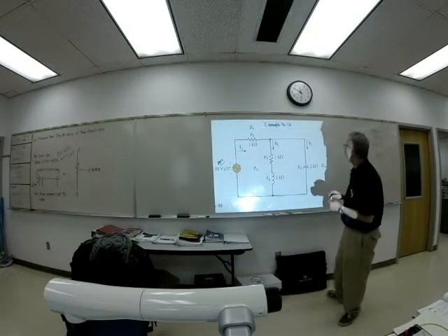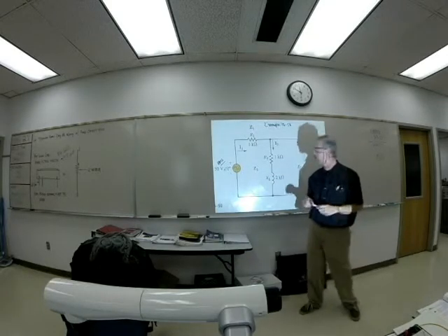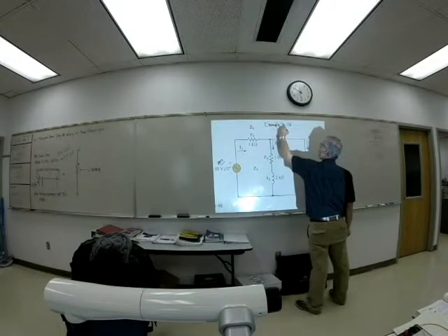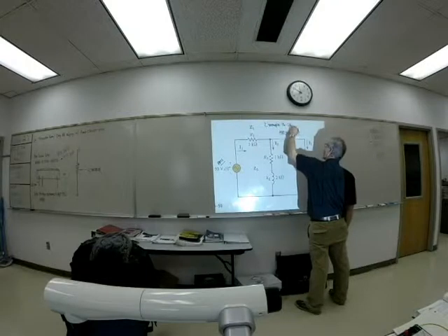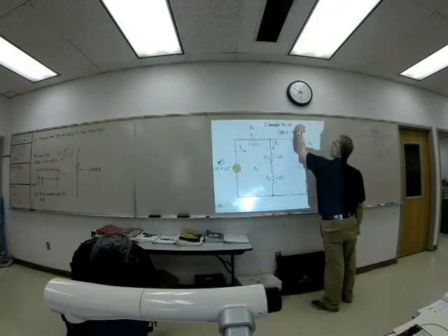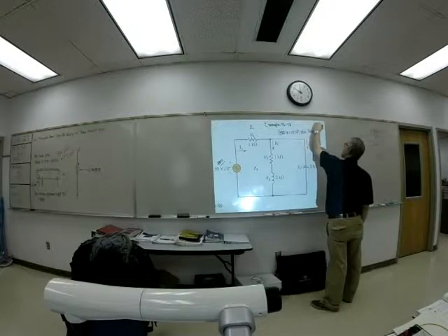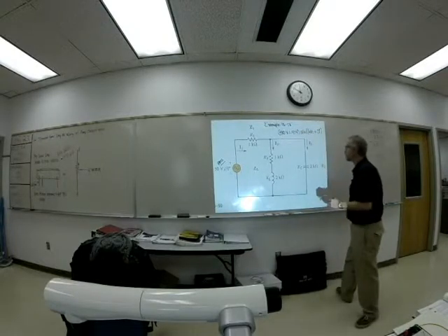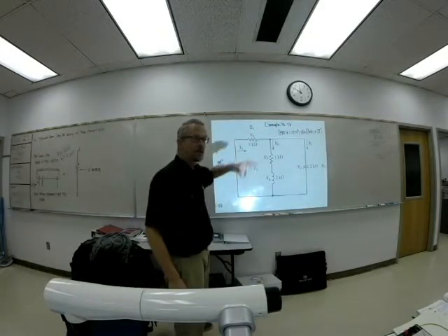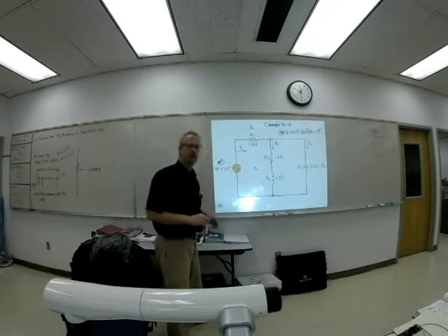Okay, so what would that actually be if we wanted to look at that voltage as a standard voltage definition in waveform or in sine form? That would be 50 times 1.414, which gives you the peak value, right? Sine omega t, and in this case plus 0 degrees. Because remember, when we use that form, it's always in peak. And when we use the form where we give the angle like this, it's always given in RMS.